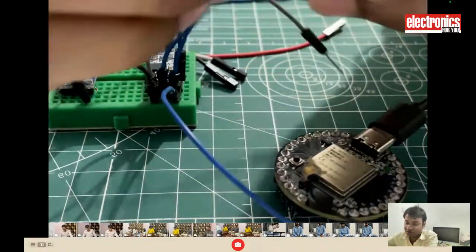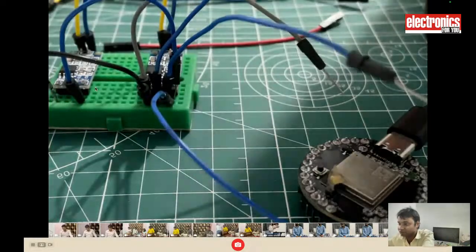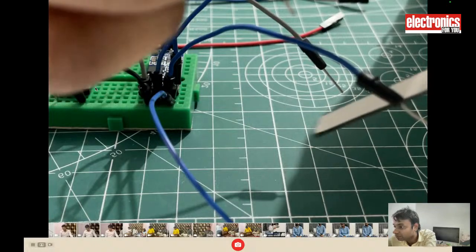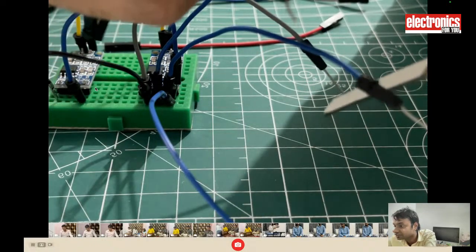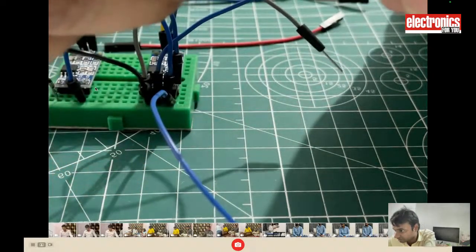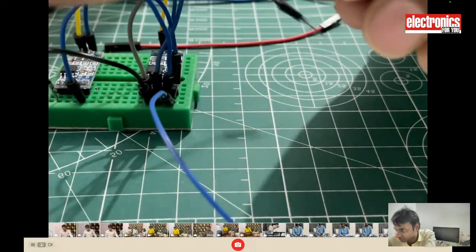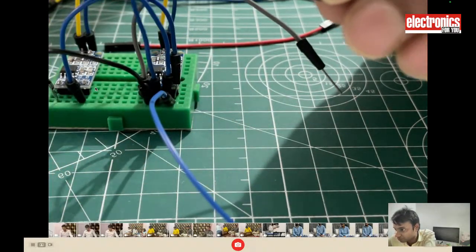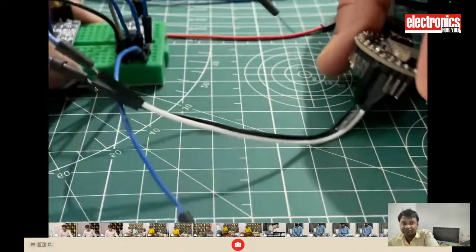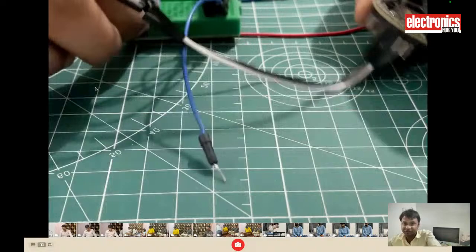on the controller, RX pin and TX pin on the controller, and then I am using the female jumper wire on this board at 21 and 1, pin number RxTX for the CAN bus, and connect this pin 21 as RX and then 22 as TX. And pin number 1 is TX. So this is my connection with the ESP board. You can check.